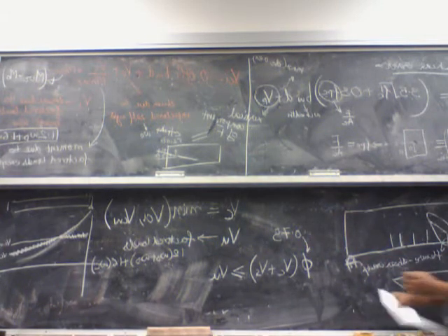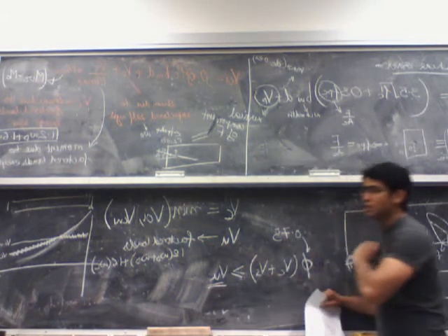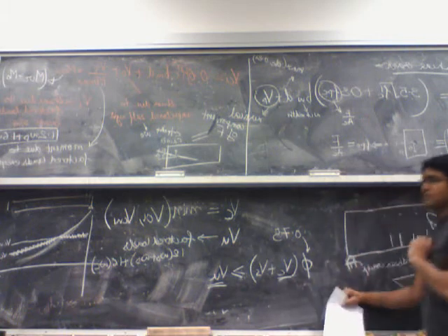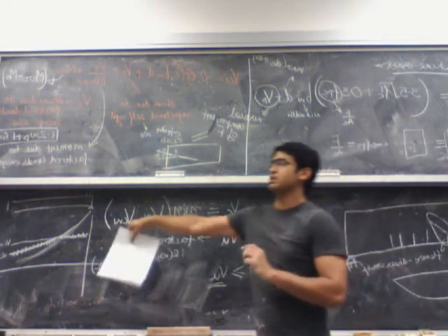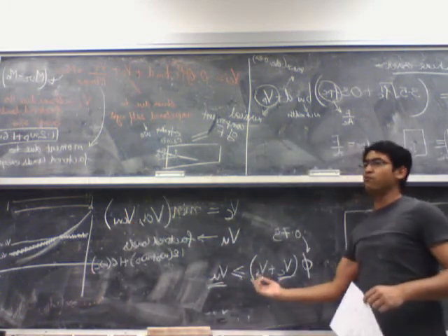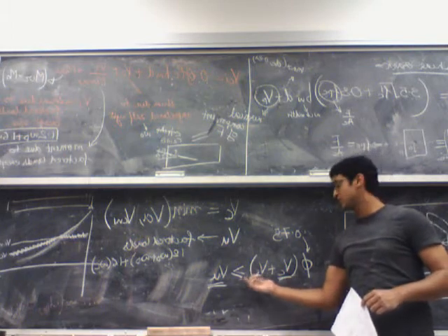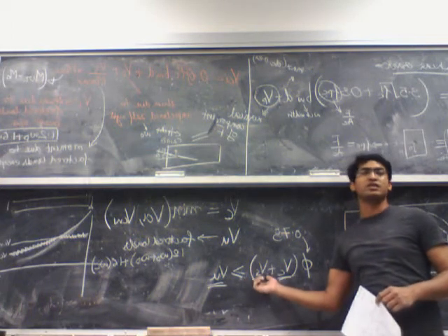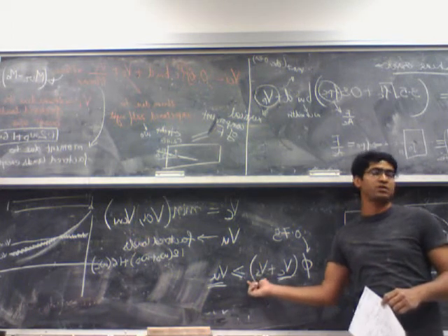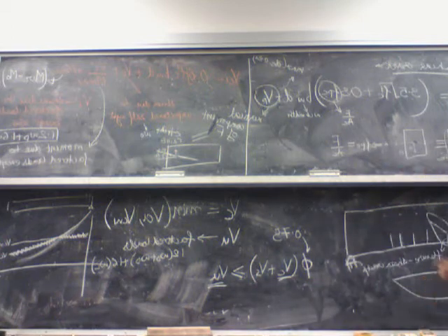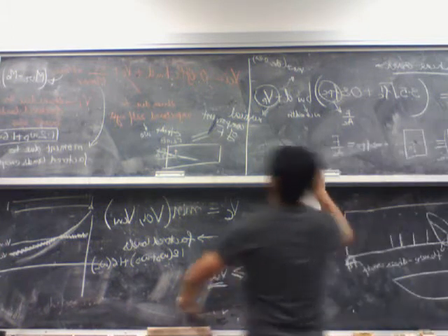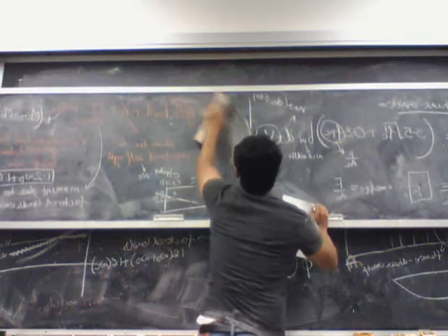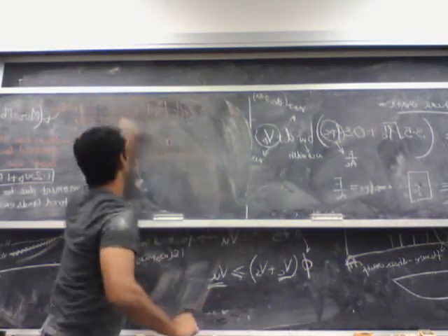So now we know the value of VU, and we know the value of VC based on VCI and VCW. I can calculate the shear capacity which needs to be provided by the shear stirrups, VS. Then VS again has a formula.